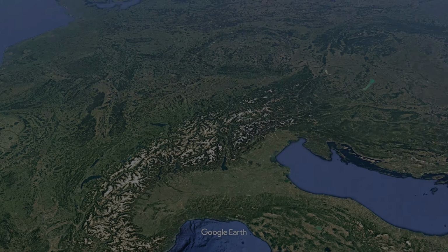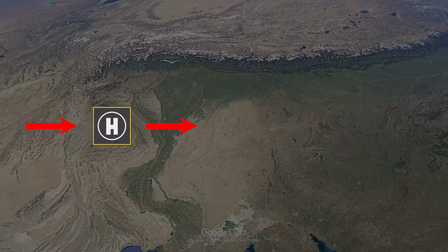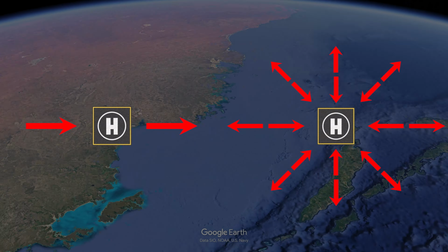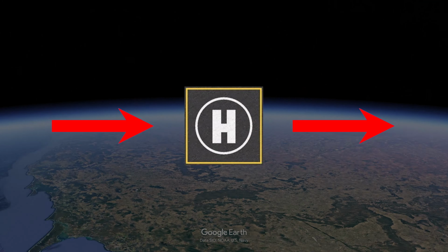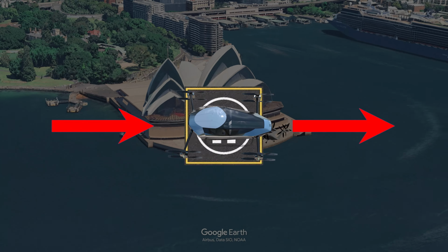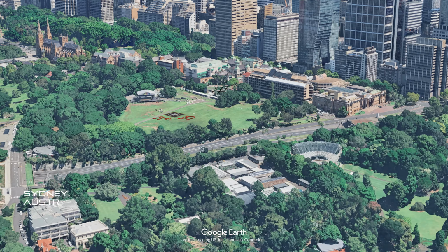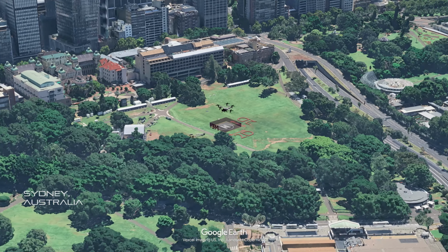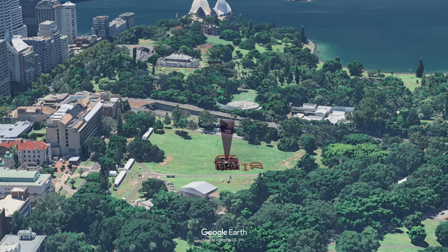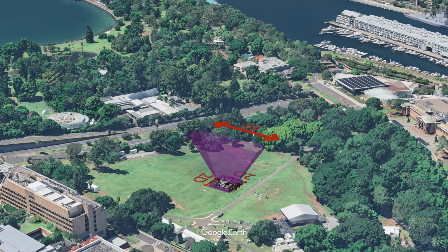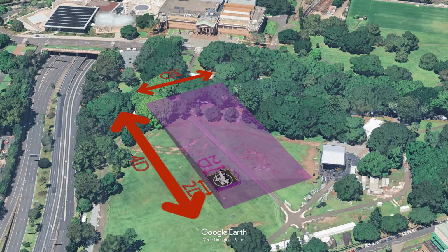There are two types of procedure volumes, directional and omnidirectional. The directional procedure volume is designed for aircraft that always follow a specific approach and departure path. It begins at the 2D by 2D pad, extending upward by 3 meters, before sloping outward to form a rectangle that's 3D wide and 4D long, at a height of 30 meters.